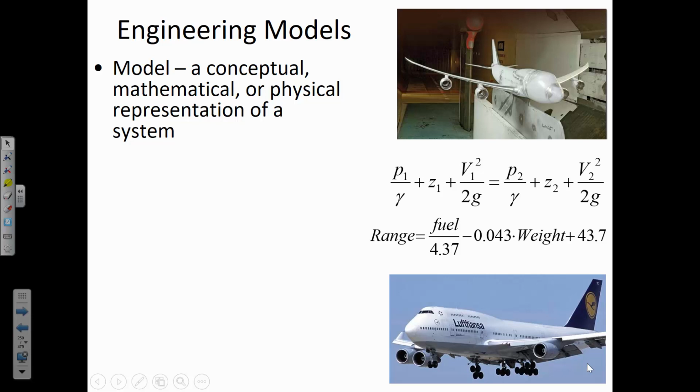The units here are all going to be meters. Z, or elevation, is measured in meters. Pressure is measured in newtons per meter squared. And then the unit weight is newtons per meter cubed. And so then that expression together, the newtons are going to cancel out, and then we have meters to the third divided by meter squared, so it's just meters. So we're adding meters to meters.